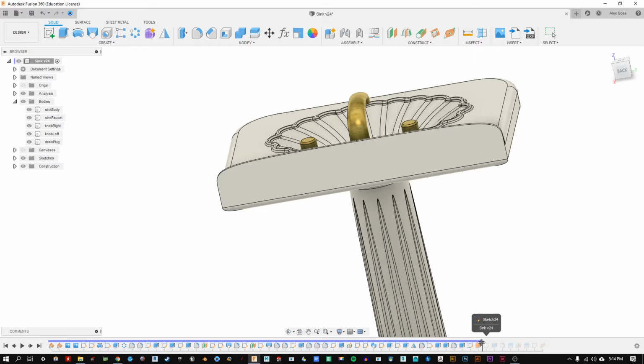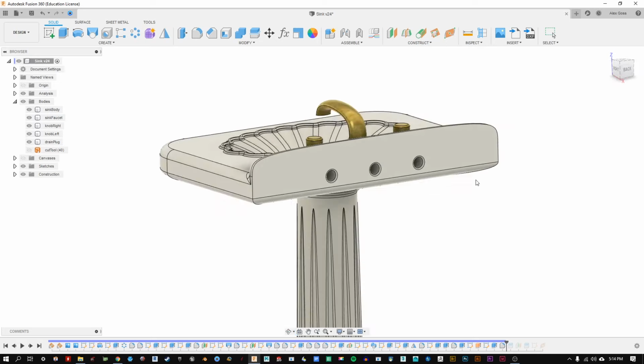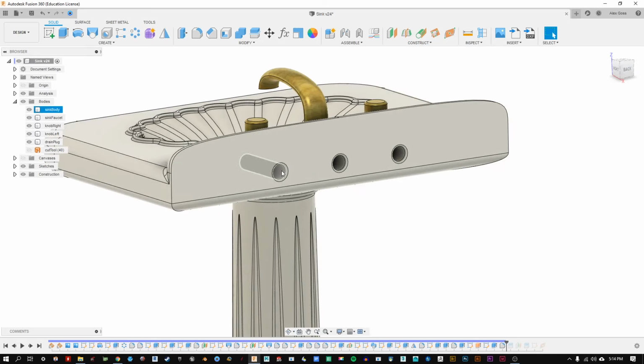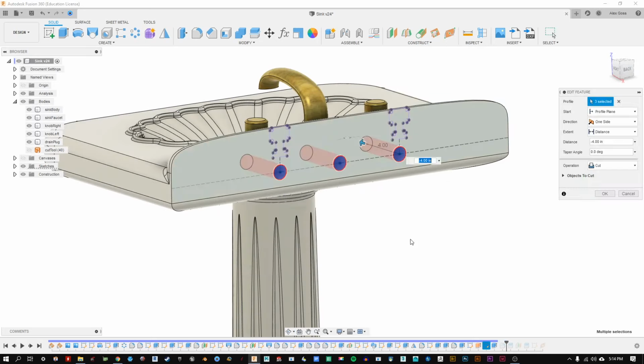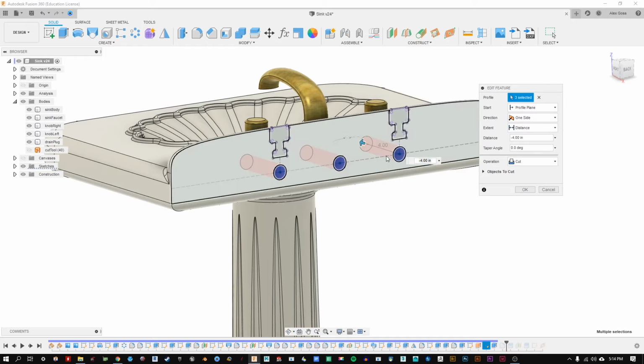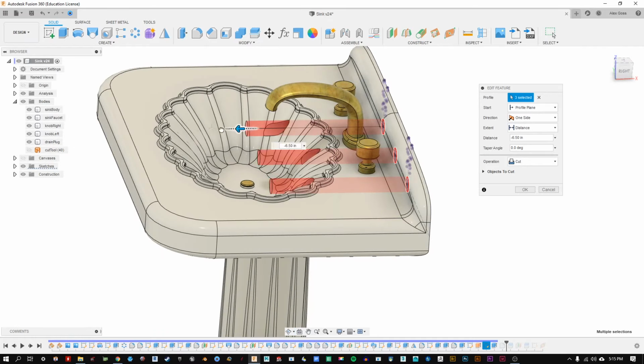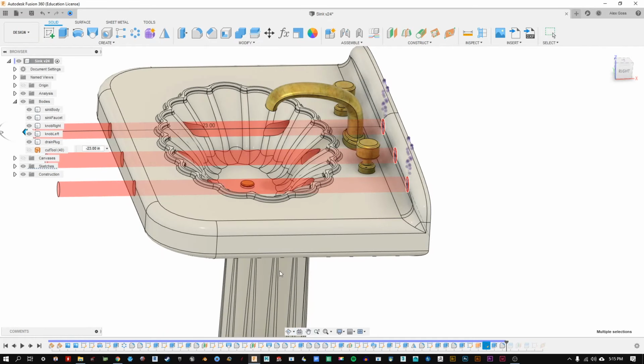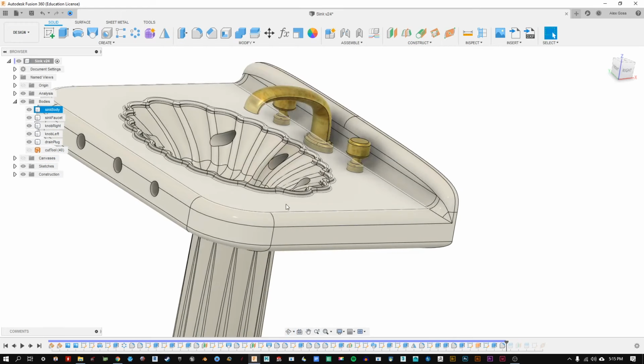So we can change not only, let's see, where were we? There we go. A profile sketch, but also we can edit that feature. We can just right click on the thing we want to change, and it'll bring back up this feature dialog. A feature is what we do with a sketch to make it into some kind of three-dimensional form. So we could have these holes go all the way through if we wanted to. Okay, if we hit OK, it'll recalculate that scene.